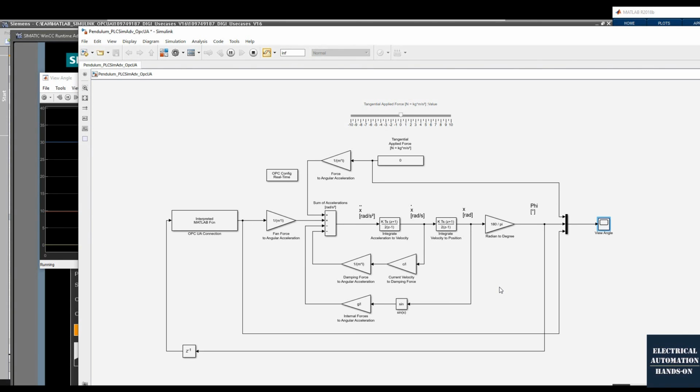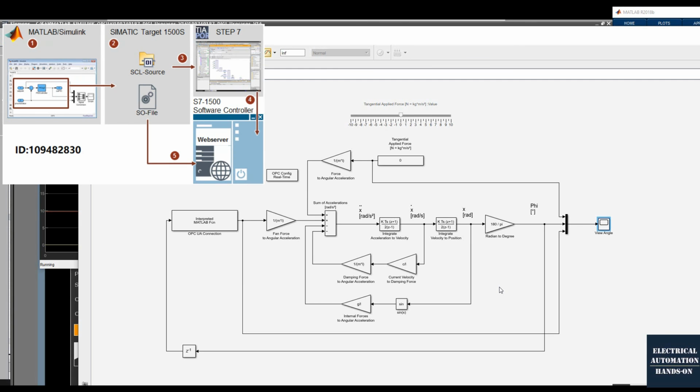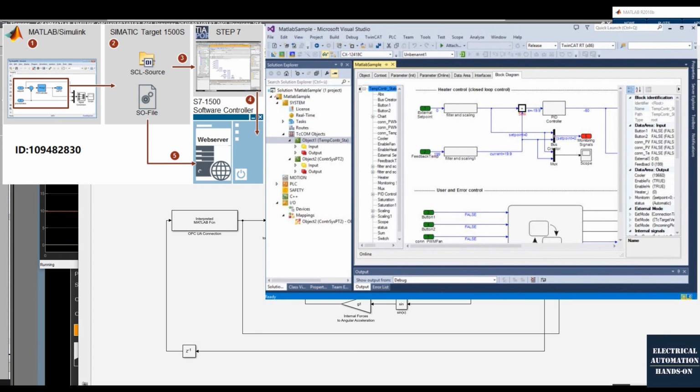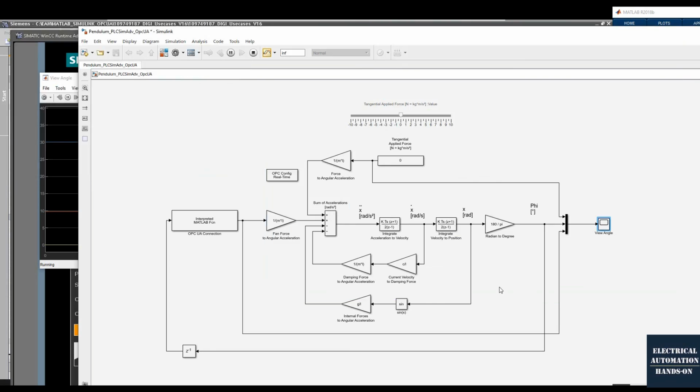Honestly, without OPC UA before, it was a little bit hard. Basically, we had to use a software controller. On the Siemens side, going back 10 years ago, they called it WinAC, and now they call it S7-1500S. And on the Beckhoff side, we had to use the TE1400. That package connects Matlab and the Beckhoff controller together. That is not quite easy, because there are so many tiny settings and environment settings in that area.